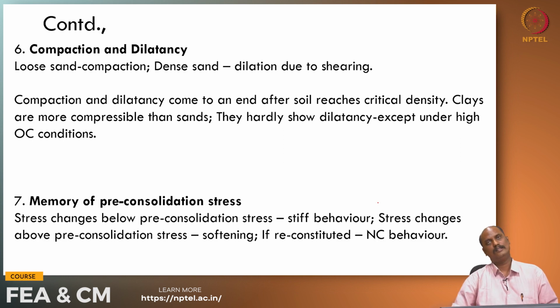The next important factor is compaction and dilatancy. When it comes to compaction or dilatancy, the concern is about sandy soils or frictional soils. Loose sands undergo compaction, while dense sands dilate due to shearing.